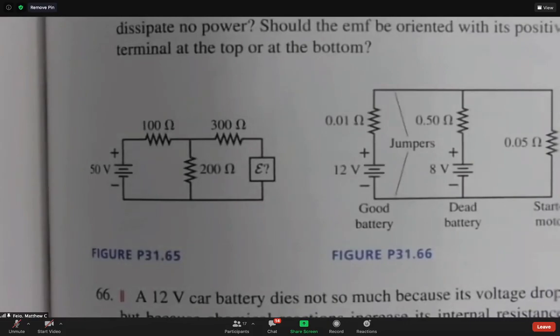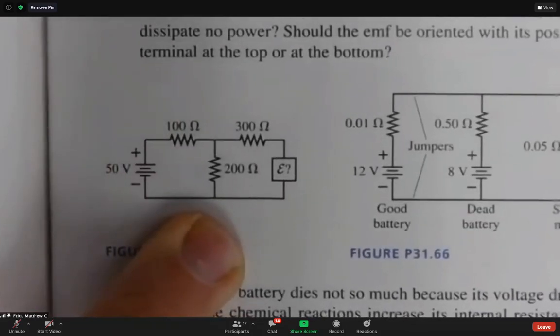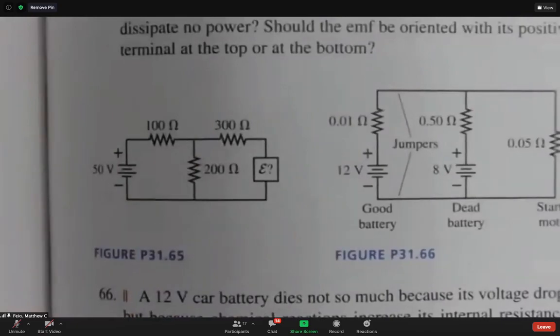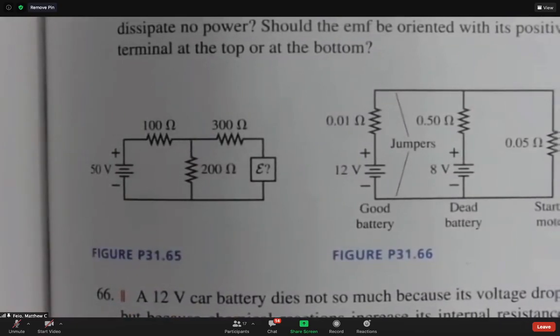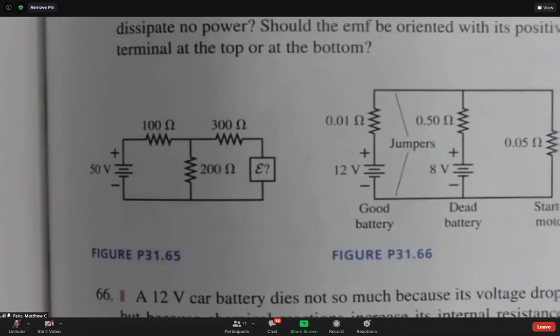One of the scenarios for the cube, there is a wire that carries no current. In one of the different possible connection points, if you do the analysis and think it through based on symmetry, you'll come to the realization that there's a wire here, or maybe more than one wire, that doesn't carry current to the left or to the right. You could interpret that very much like this wire carrying no current. There's a wire with a resistance, but the two ends of the wire are connected to the same voltage. Neither point's higher than the other, so current doesn't want to flow downhill in either direction, so it doesn't flow.